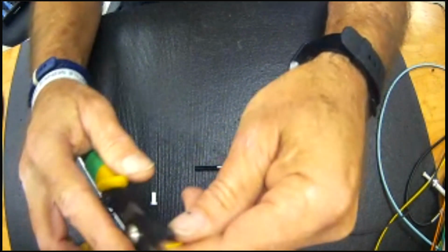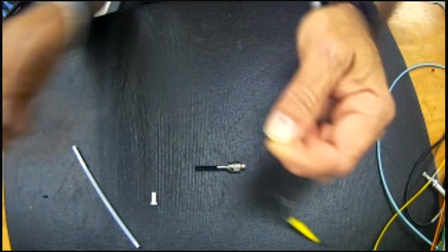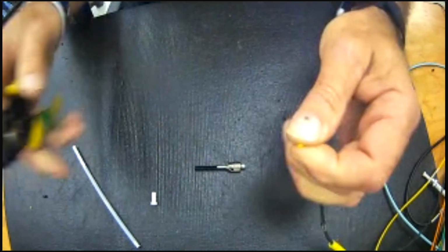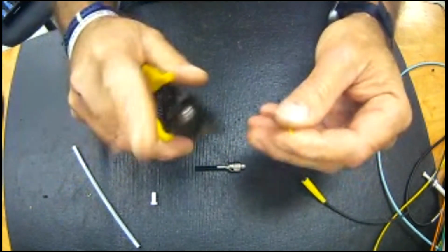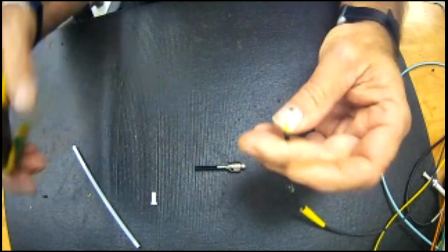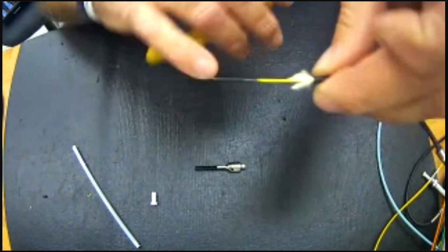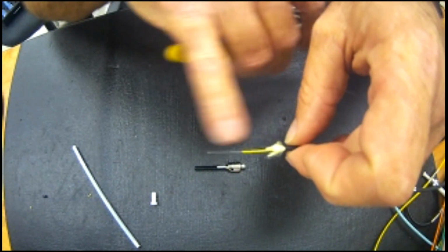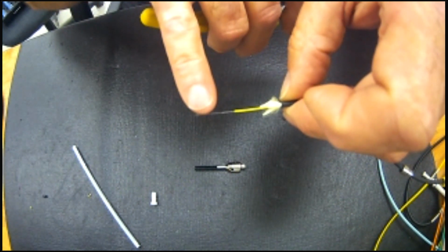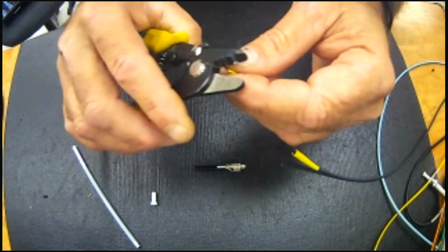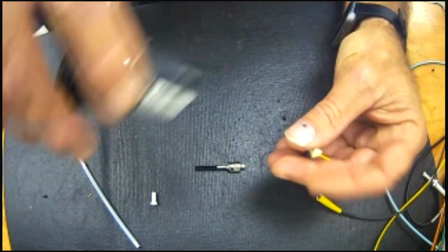Now, the strip is again with the same tool, and it's nibble because this is a tactical jacket internal to this. I have to take it off in small pieces. If this was PVC or one of those inexpensive Chinese patch cords, I could probably remove larger pieces of it. Now that I've removed the 900 micron buildup internally, you can see, I think, the 125 micron core. And there's still some residue on it that I have to remove with the last and final die of that.